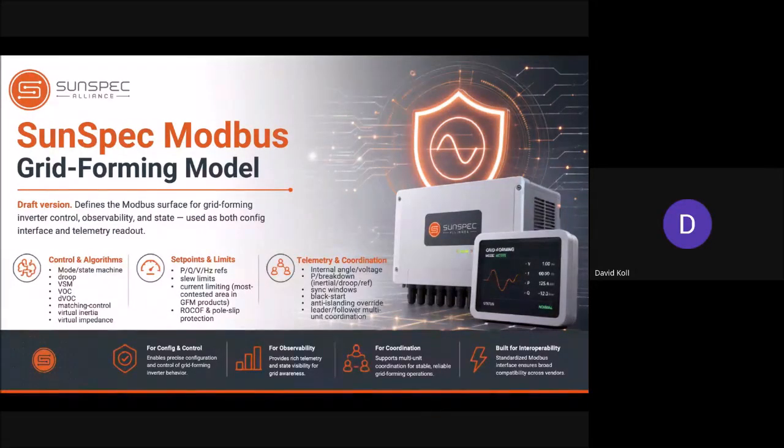The issue with all the DERs going offline when the grid goes down is that, unless they have a battery backup, they're unable to produce energy to their loads and not able to create a grid from scratch, commonly referred to as a black start, by creating their own inertia. This leaves the load they're supporting without any power until the grid is re-energized and the unit can once again sense that the proper phase, voltage, and frequency is there to synchronize to export power. In areas where the power grids are largely grid following, when DERs are looking to find and follow a leader to synchronize to, systems begin to trip offline. Other systems which are following those systems also begin to trip, which triggers a ripple effect and system instability.